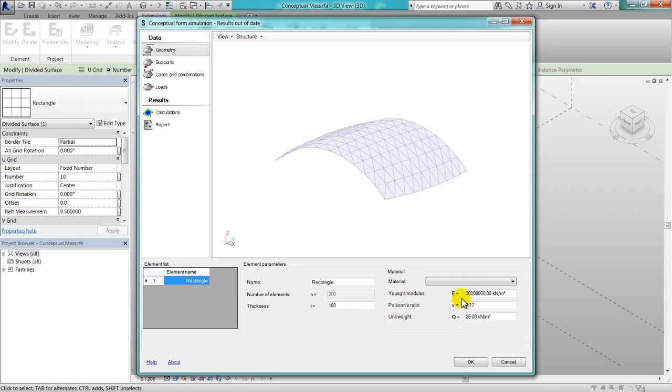All other values like E modulus, lateral strain and weight will jump back to the default values as soon as the geometry is deselected. Go to the View tab up here, hit Selection and select the geometry again and see that the lateral strain 0.2 will always jump back to those default values, which reflect some sort of concrete.